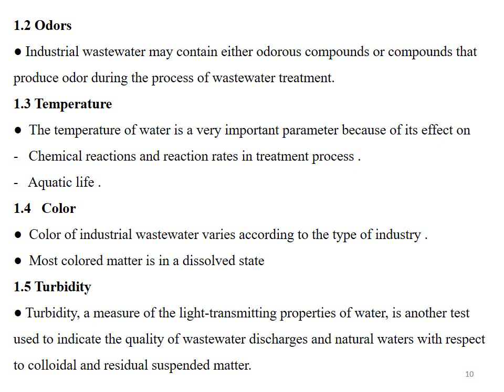The next physical characteristic of wastewater is turbidity, which is the measure of the light transmitting properties of water, and it actually depends on the colloidal and residual suspended matter inside the water. This is actually a test used to indicate the quality of wastewater discharge and natural waters with respect to colloidal and residual suspended matter.